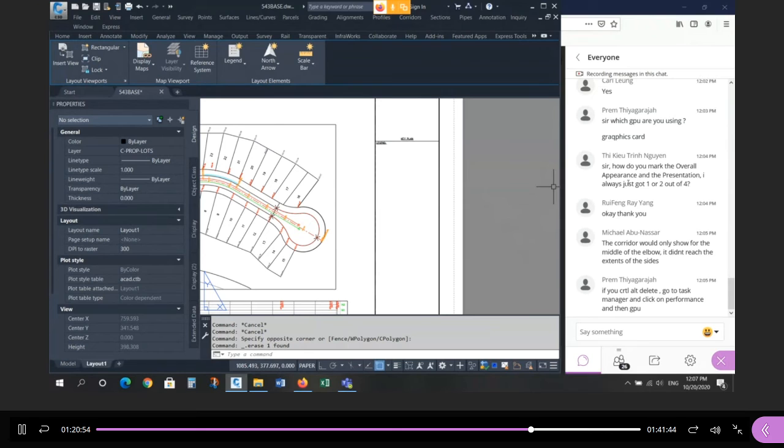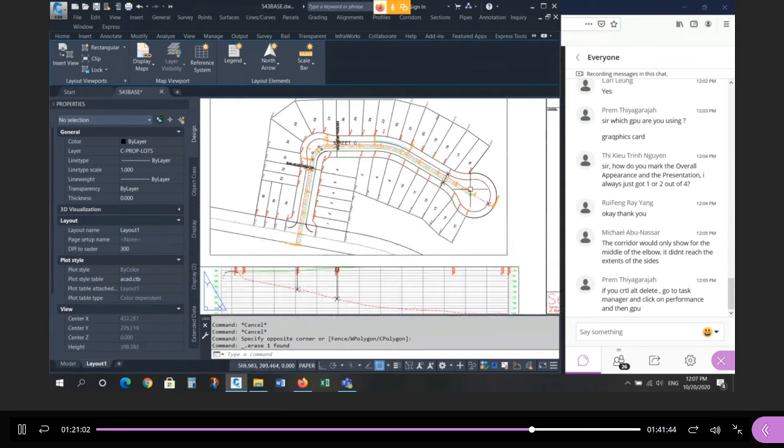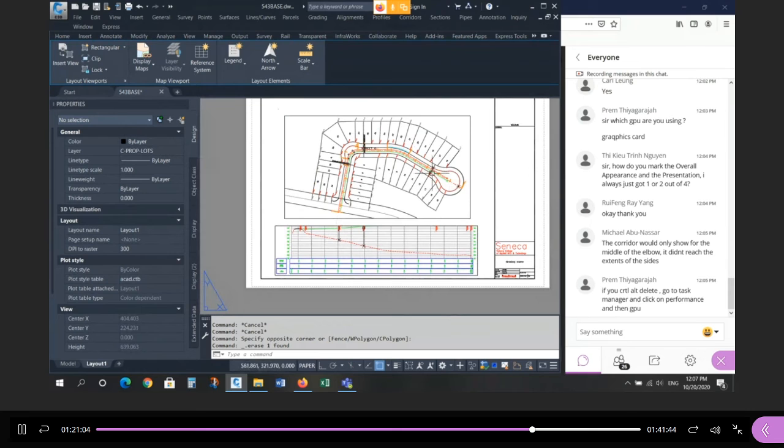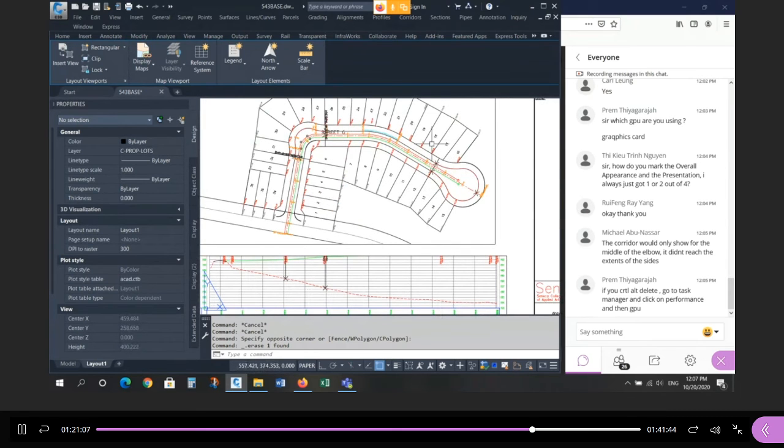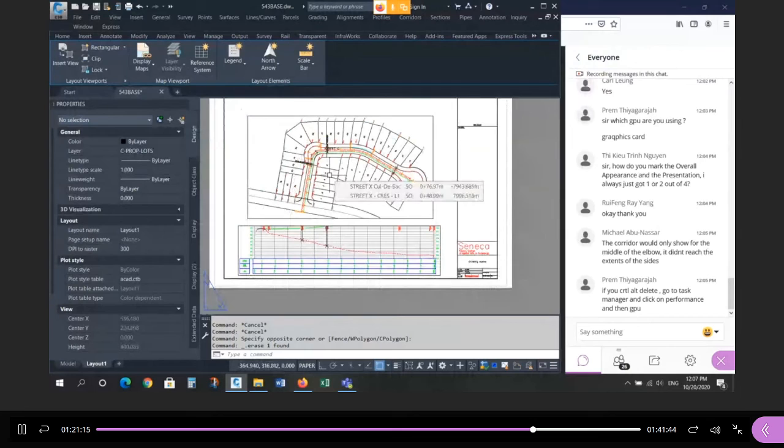So that was one issue related to the legend. The legend was the biggest issue. That's one mark, what you show in the plan view. When you're looking at the plan view, you shouldn't see anything related to grading, right? So there should be no existing ground contours or surface information here. There shouldn't be anything in the plan view that's not related to servicing. So no elevations, no contours. I made sure that you weren't showing anything like that.